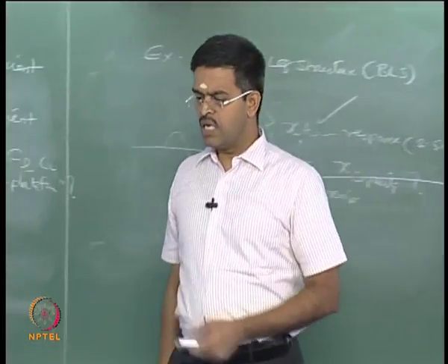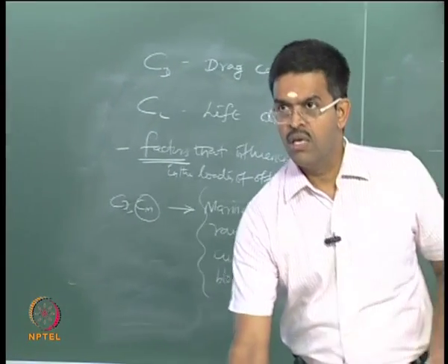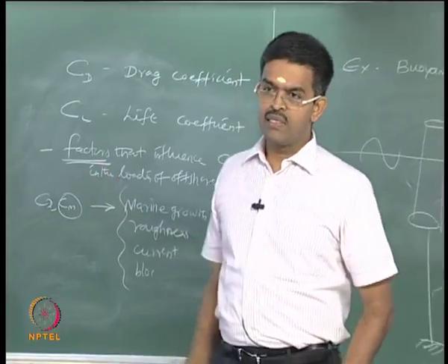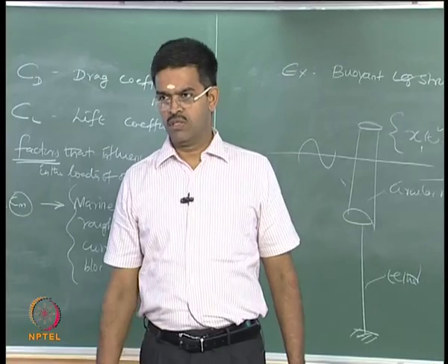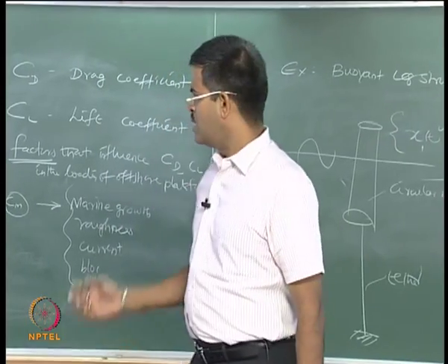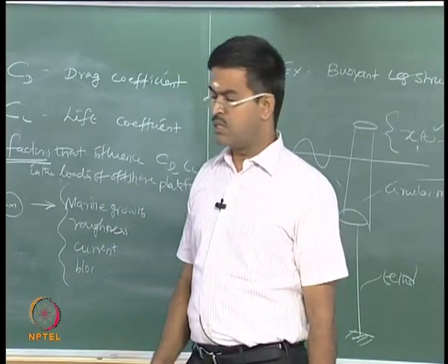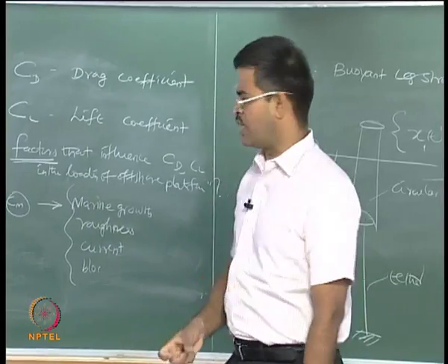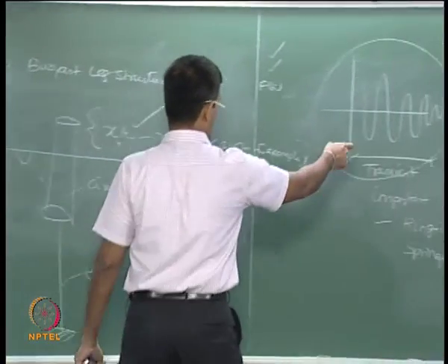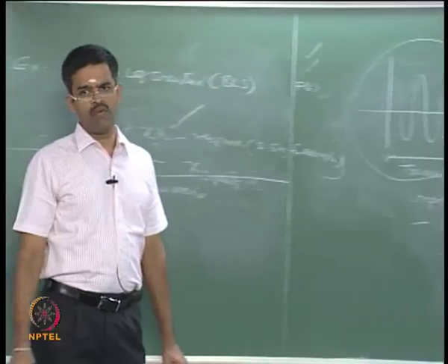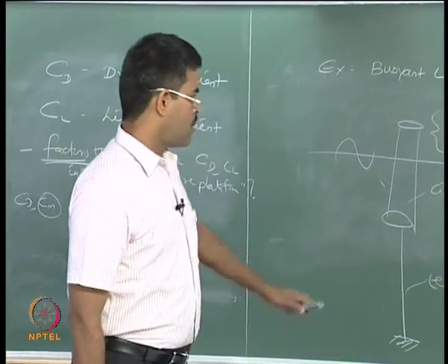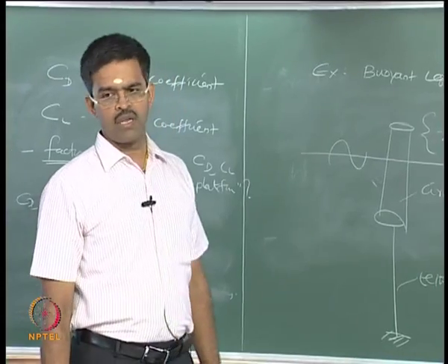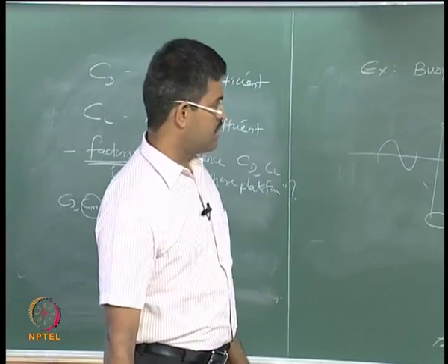Therefore, if you have a lift force with multiple frequency bands, it is important for me to understand the frequency band and the amplitude of these forces. Not necessarily that multiple frequencies may have a lower content, but since the frequency content is predominantly representing my response function, I can always have resonance even in the transient state itself. We will talk about ringing and springing responses later, in compliant structures like TLPs and spars.